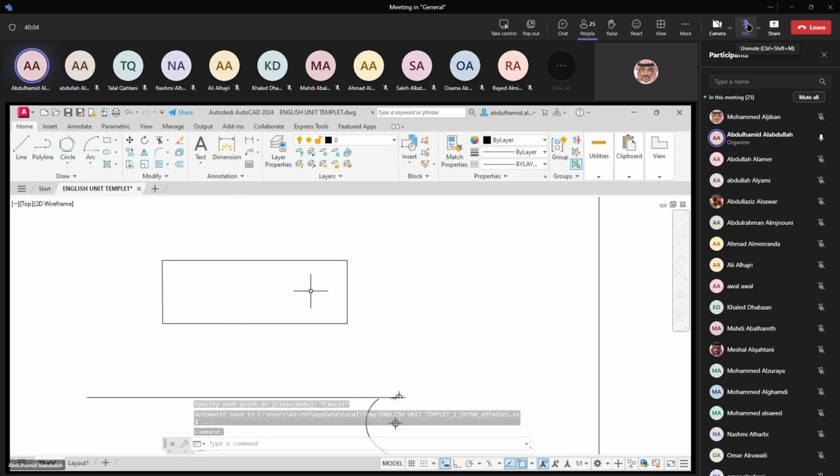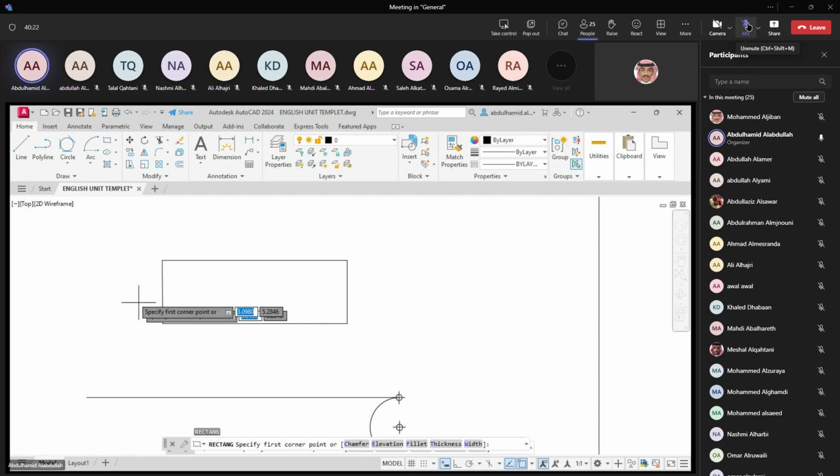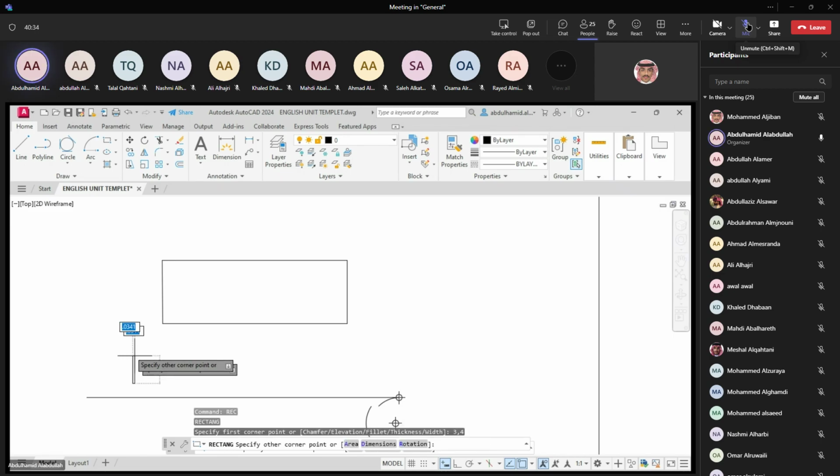But the good thing here, we do have an option to create a rectangle geometry within a couple of clicks by coming and clicking on the rectangle in here, or by typing REC for rectangle, click, and then it will ask you to specify what is the starting point, whatever the number, let's say 3,4, for example, and just give it what is the value of x-axis.